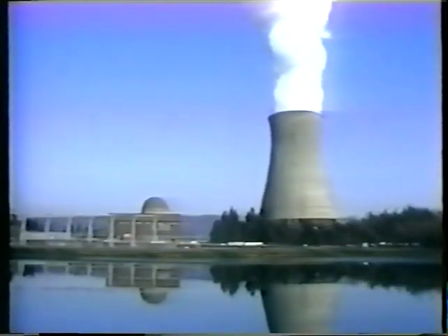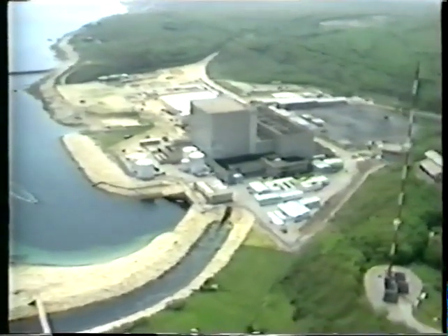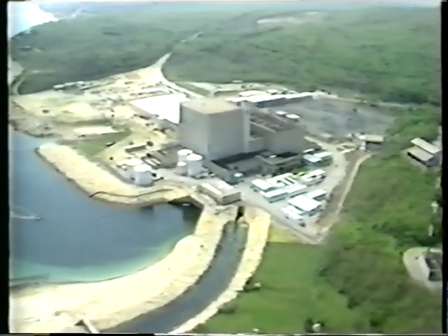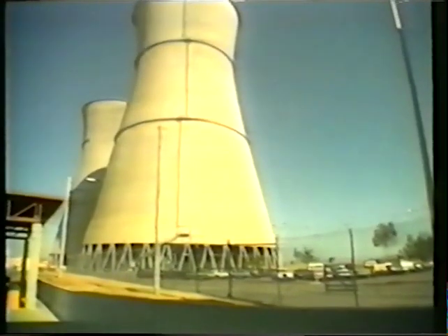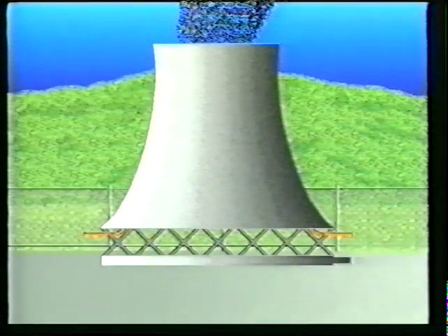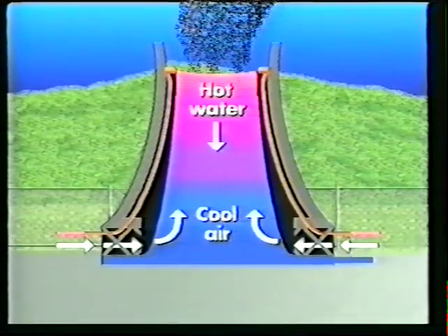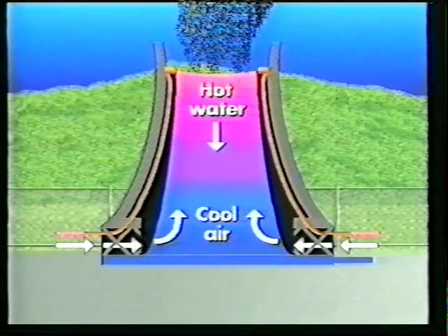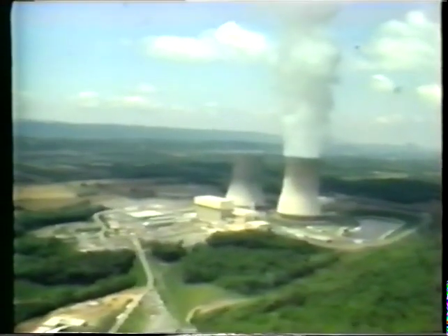However, it is usually illegal to warm a river because it will affect the environment. So after the cold water has condensed the steam, it must be cooled in cooling towers, ponds, or canals before being returned to rivers. Cooling towers are hollow inside. Water is sprayed into them while air is blown up. Some water evaporates, cooling the remainder. This way, the atmosphere absorbs the waste heat.